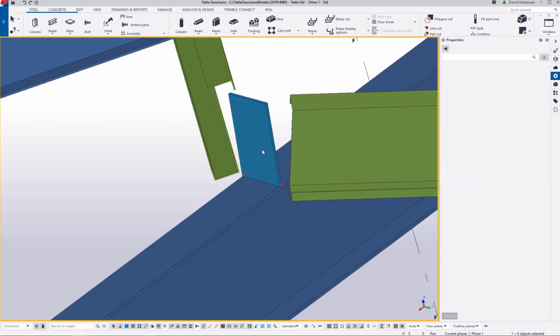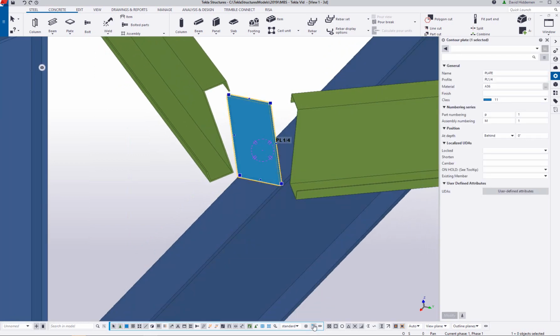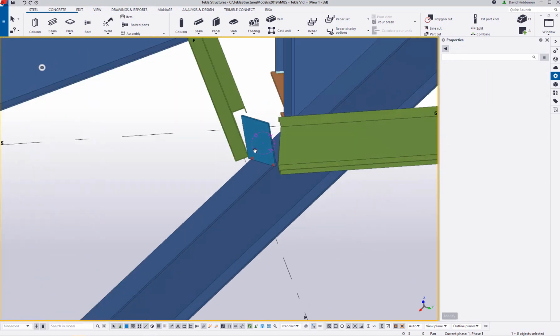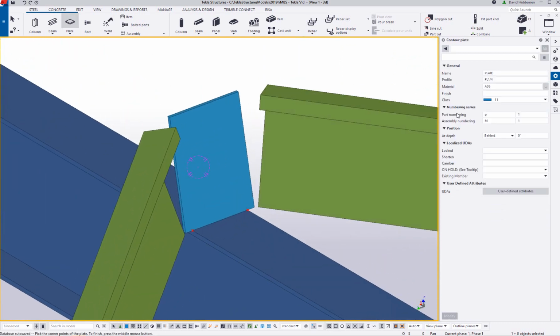So you can go ahead and type in those dimensions, but I do want to show you how you can use that direct modification we showed earlier. Here you can click on an edge and then type in a dimension and automatically upsize that edge of the plate. So very quickly being able to resize those objects.